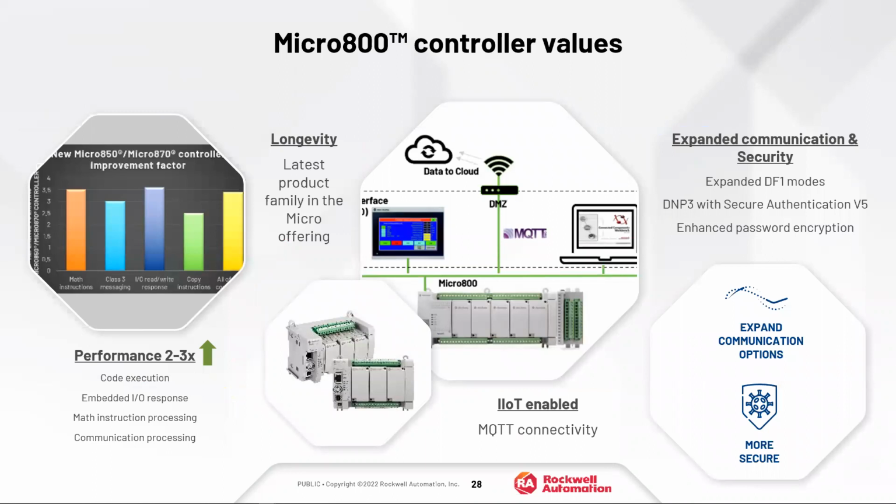Now, the Micro 800 is actually probably one of our lowest cost processor PLCs by far. Eight inputs and four outputs. The smallest controller really has a starting point of around $100. So this is our small controller. It does have a purpose-built HMI for it, which is the PanelView 800, a low-cost HMI. Size limitations are, I want to believe, 4, 7, and 10 inches. So that comes packaged with it.